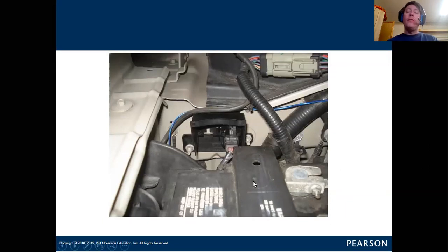But this little hat that's on there, if you have a vehicle that has a four-wheel drive hub issue and there's water in the hose, go and check the other side. It's probably got water in it too. And then go up on the top of the passenger side with the hood up on the firewall and see if that little hat is there. If that little plastic cover is not there, you need to buy one as part of the job and install it. And it's a pretty good chance, for the CYA here, you're probably going to want to do both hubs and that switch and that hat. Because if you've already got water down on the other side and it's not making noise yet, it's probably going to start making noise pretty soon.